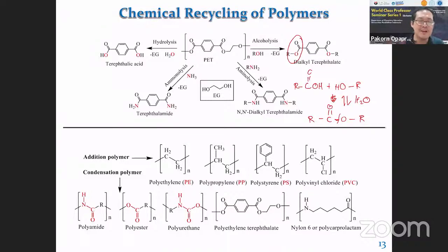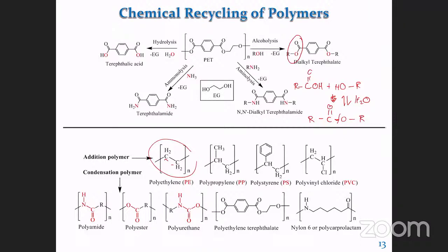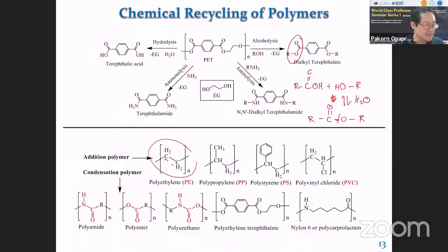So the majority of degradable polymers are polyester, containing ester bonds in the chain, compared to polyolefin, which has only carbon-carbon bonds. This carbon-carbon bond is very strong, so it is very hard to break. Therefore, polymer that contains only C-C bonds in the chain will not be degradable. So that probably answered the first question.